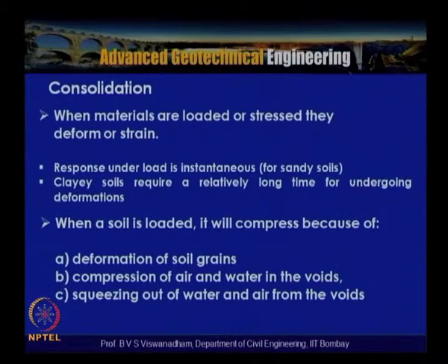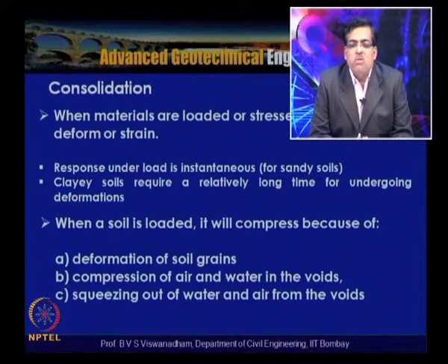Consolidation: basically, when materials are loaded or stressed, they deform or strain, which we have seen in the previous lectures. When the materials are loaded, the stresses are transferred to the ground, and the response under the load is instantaneous for sandy soils. For granular soils or sandy soils where the permeability is very high, the response under the load is immediate, but fine grained soils like clay soils require a relatively long time for undergoing deformations. So we have to demarcate here: the response under the load is instantaneous for sandy soils, and clay soils require a relatively long time for undergoing deformations.